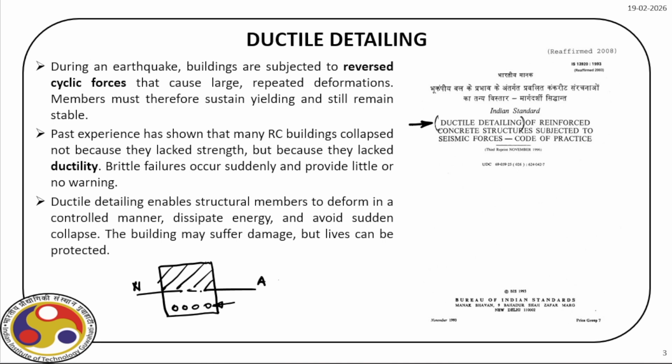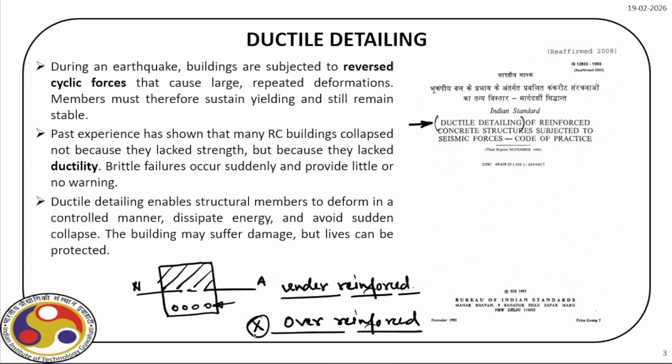During that discussion, we also developed what is called an under reinforced section. We developed the mathematical models for this under reinforced section, and there we recommended the design of under reinforced section and not the other options. What we had is over reinforced section, right? This we did not recommend. However, under reinforced section we prefer. In between these two, there was something called a balanced section. Let us not focus on that for the moment.